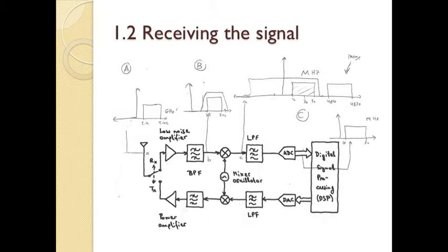So this signal will have an image that resides at 4.81 GHz. In order to get rid of this image frequency, we will send the signal through the low-pass filter, which in this case is going to eliminate the image frequency and take the wanted signal to the DSP, as shown in the last figure, which has only the frequency that's wanted.